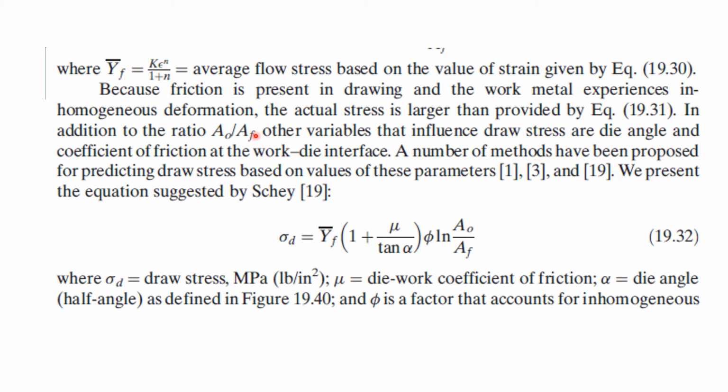As we discussed previously, friction is unavoidable in the process. There are many ways to predict the draw stress, but here is the equation presented by Schey. The draw stress can be predicted using this equation, where we consider the die-work coefficient of friction, the die angle, and a factor that accounts for inhomogeneity of the process.